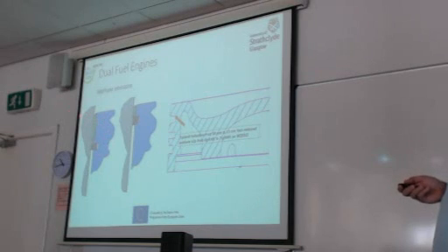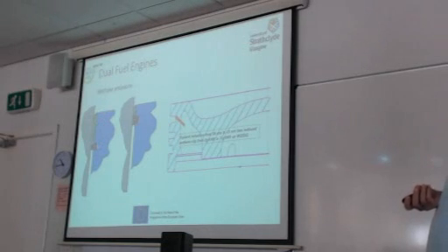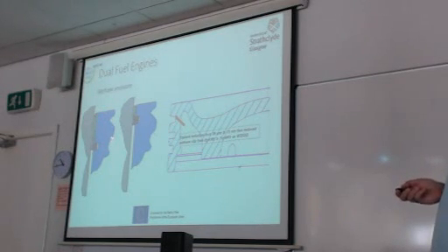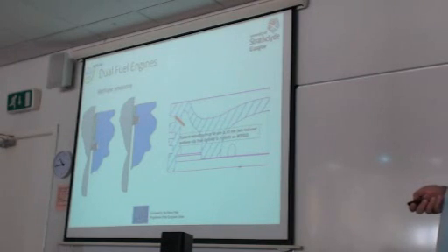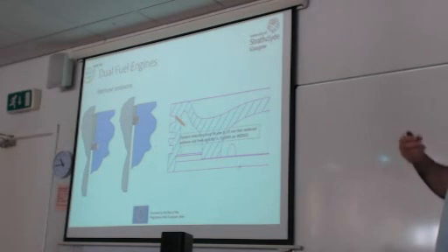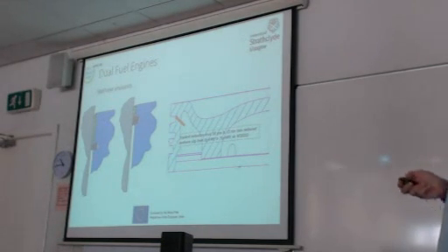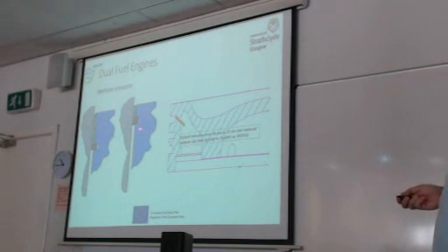Methane emissions are a very important issue for dual fuel engines. Why? Because there are these crevices, and we expect that you can understand which components of the engine are shown. You have here the piston of the engine, the liner, and the piston ring. And of course, there is a crevice, a gap between the piston and the liner, and in all these gaps a mixture of natural gas and air is trapped. This is a source of burnt hydrocarbons, because combustion cannot occur in these crevices, and as a result, hydrocarbon levels